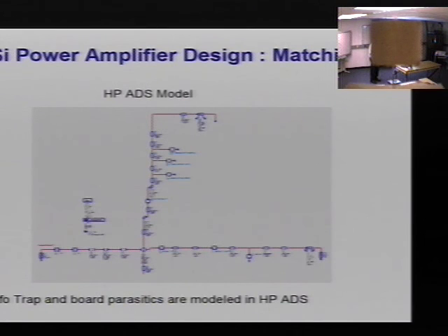One of the ways to prevent a second harmonic from happening, or to trap the second harmonic, is to use a quarter wavelength at fundamental, and that's still very difficult to do. So we tried to institute some components over here as a trap. This is the output of the PA, and then there's the third stage supply coming in. So that's where the power is coming in.